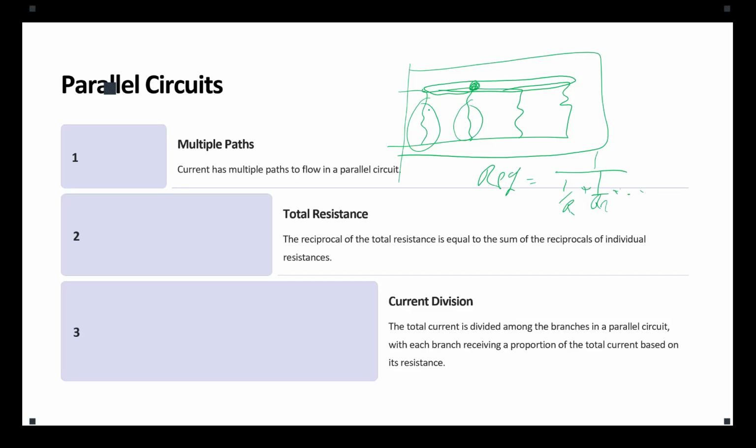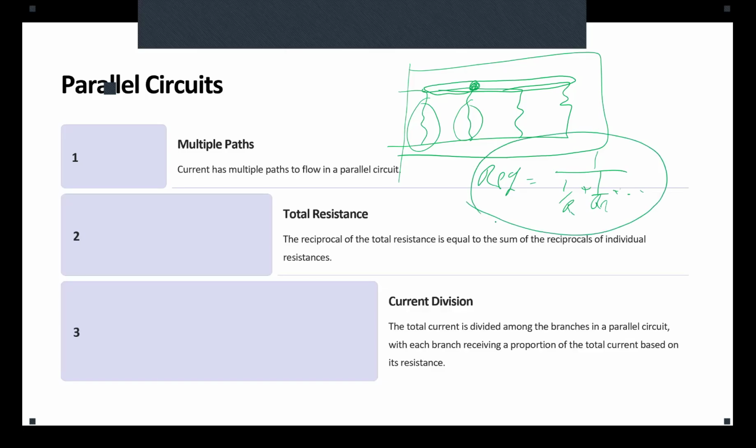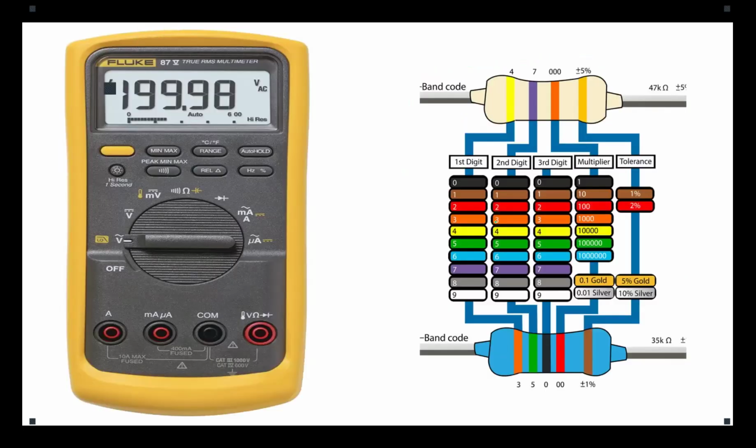You can also use the formula of the KCL and Ohm's law to find the values of current division. Now, if you have a complex system, you just need to apply each of these two step by step to a subsystem to simplify the subsystems, and then move forward step by step to simplify the whole system to one resistor. We are going to see that in one of the examples in our lab assignment. Now, let's go to the lab.